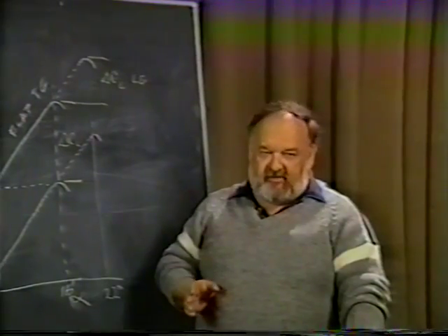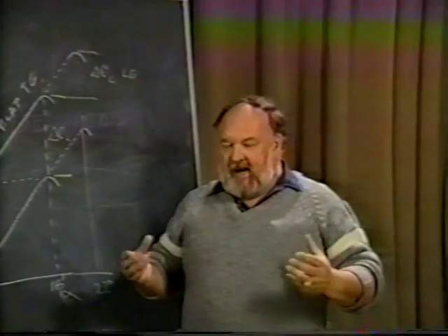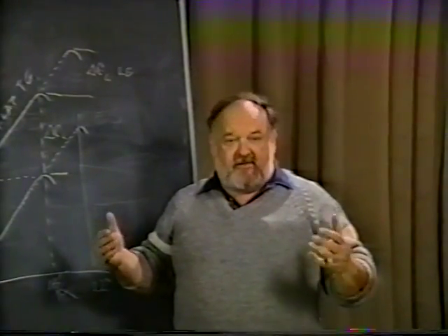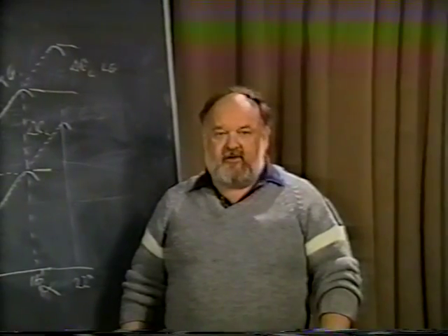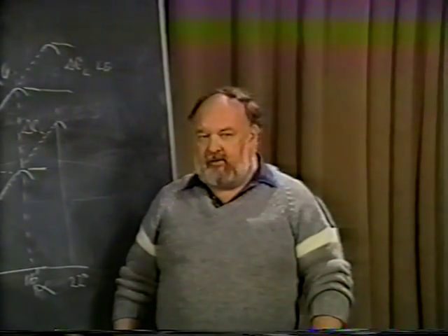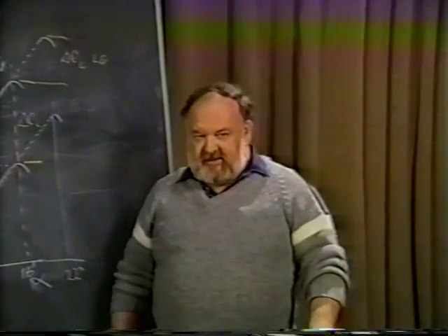There are some places where obviously you don't want to use them. A sailplane. A sailplane ends up with a lot of wing area, a high aspect ratio wing. It doesn't really land at a low speed. It doesn't need to land at a low speed. It has a relatively low wing loading already. Therefore, a trailing edge flap for high lift devices is not practical.